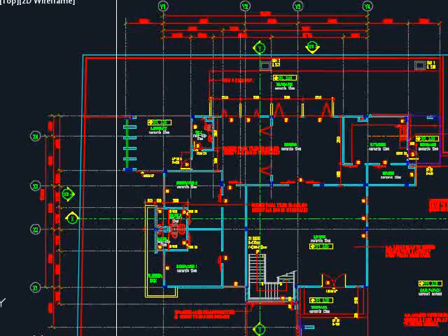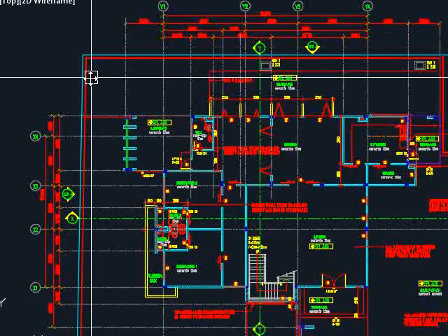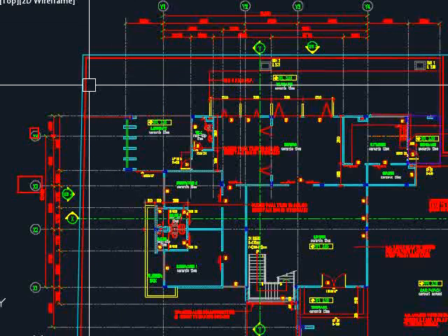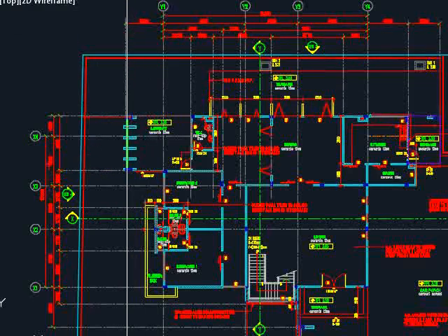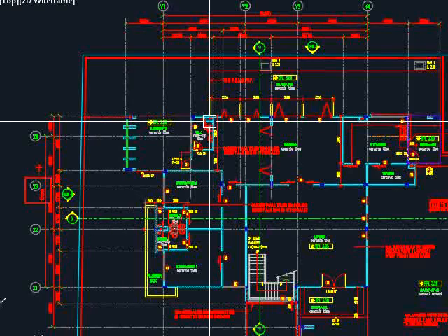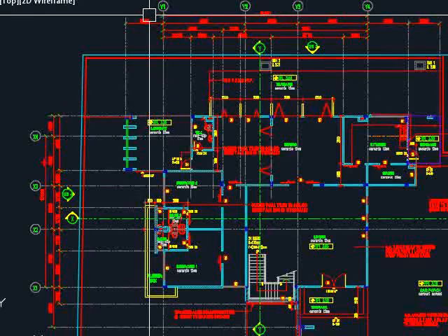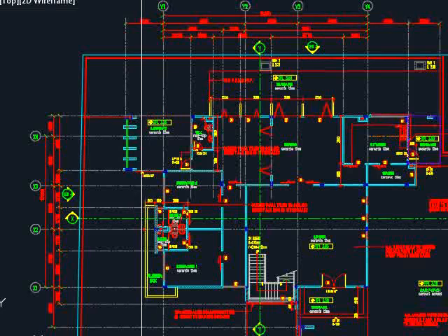Of course, for easy referencing, especially when there are grid lines somewhere in between the main grid lines, something like this, you will need to provide other numbers for the grid lines as subgrid lines for the existing main grid line here. Probably I will put this as x3a, and if I have another grid line, it will be x3b. A similar principle applies to the other grid lines here if it is not clearly stated in the architectural drawing.